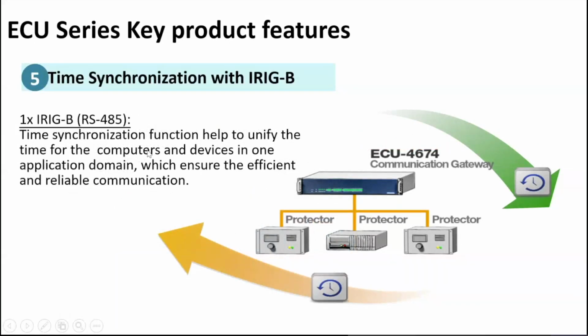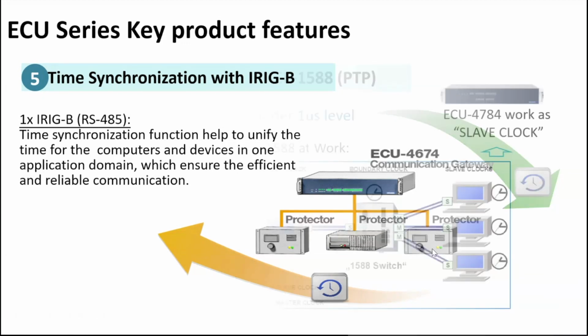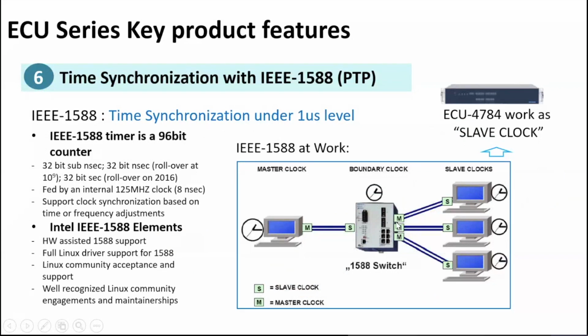For our ECU series, we also support time synchronization with IRIG-B by using the RS485 port. This is a standard format for transferring timing information. We also support time synchronization with IEEE 1588, which is PTP, the so-called Precision Time Protocol. This is a protocol used to synchronize the clock throughout a computer network.